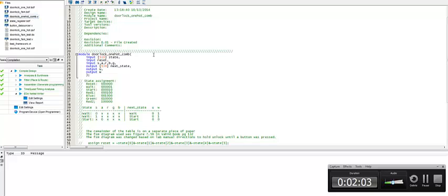Notice, first of all, in order to do this, I have to have more flip-flops. I have to use a flip-flop for every state. Since I have 6 states, with this particular encoding I now have 6 flip-flops associated with states. So my input has 6 flip-flops and my output has 6 flip-flops, state and next state, each using 6. I have a reset that I have to keep, because all of the flip-flops are set to 0 initially.